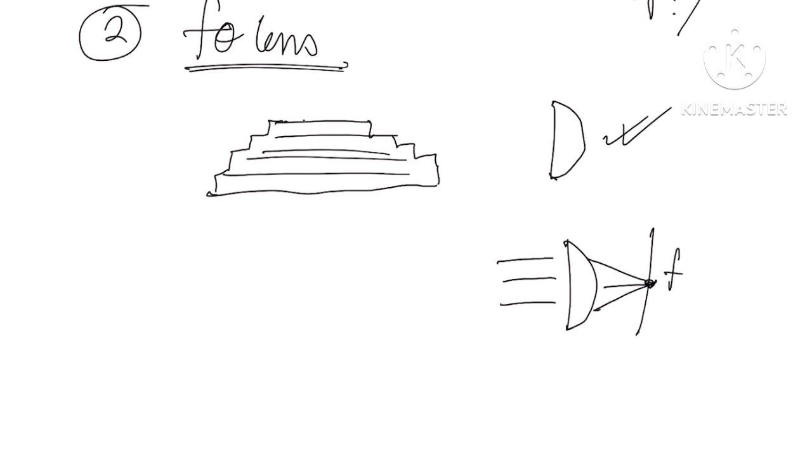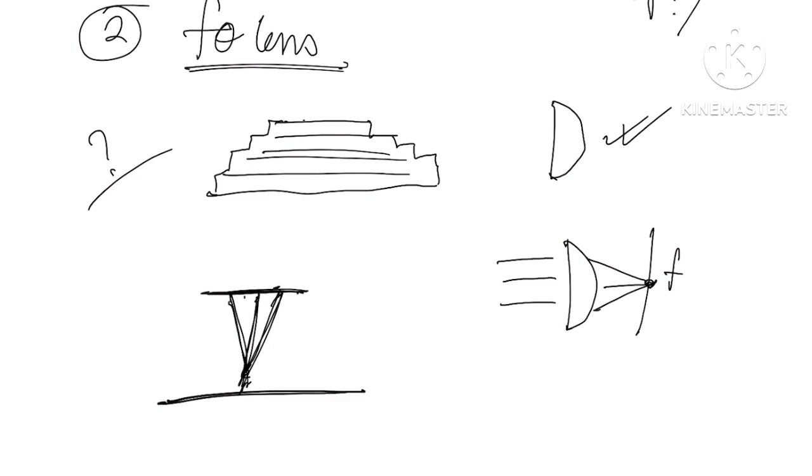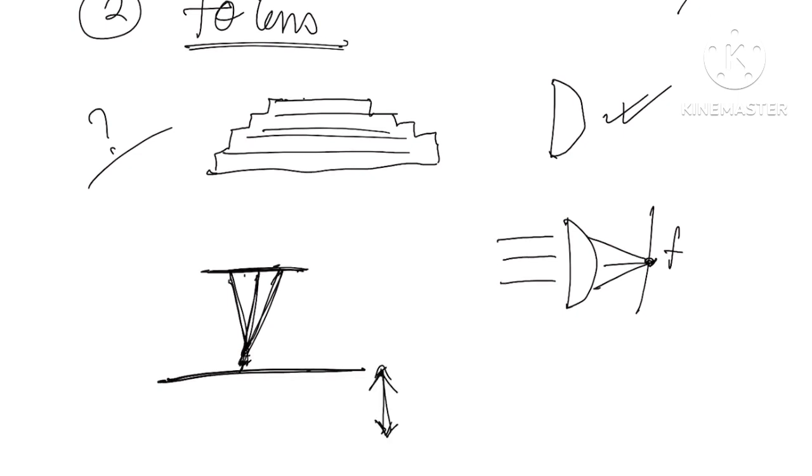So here is another question: why is an F theta lens used? Why are normal lenses not used? Basically in powder bed fusion, the source from which the laser is coming will be fixed. This is the powder bed, which can move in Z direction only. So if the bed size is this much, this laser needs to move from this end to this end.